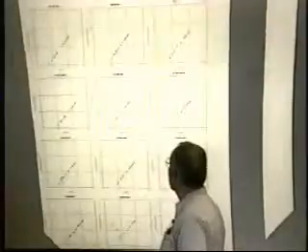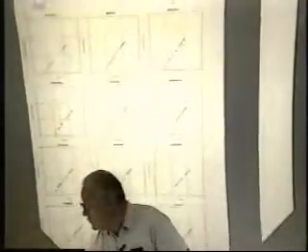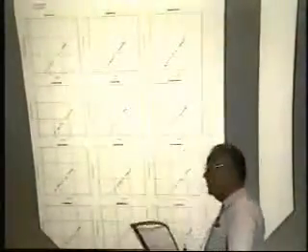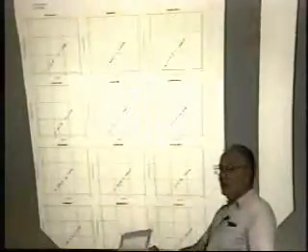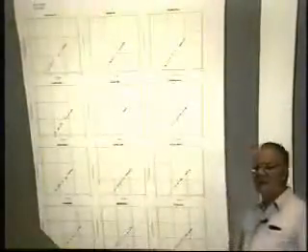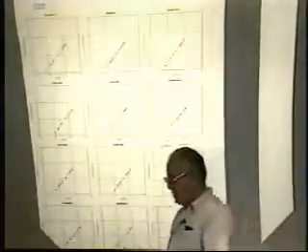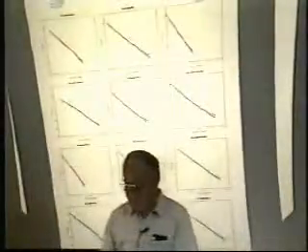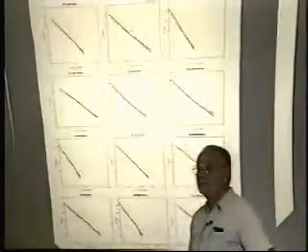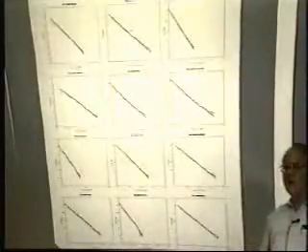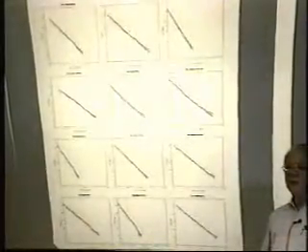This is the same one. The same case, but now we've thrown away 20% of the volume. If you look at this P over Z, and that deliverability, you say, boy, that's a perfect match. Which one's right? Well, if you go back to this one, what's wrong with it? Well, the layer pressures are all equal. And we measured 320 pounds in one, 120, 140 in the other one. That's what's wrong.